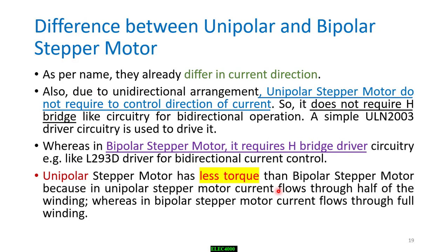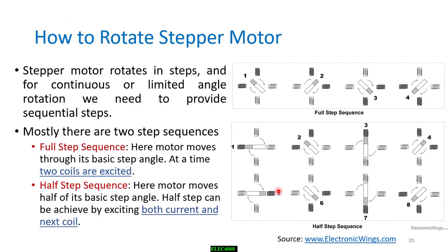Now, let's go into details on how to control a stepper motor. If we want to do it in a full step, you can see that if we energize these poles over here, the rotor will move halfway. Then here is another halfway, and here we have 4 steps controlling our motor.